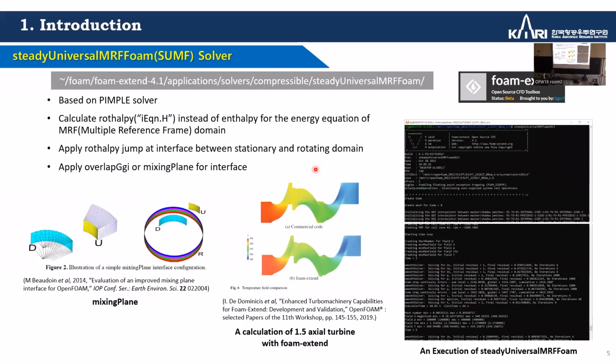What we found is that some researchers have already done their work, for example with an interface like a mixing plane here, and some researchers have already done work on the compressible MRF solver. MRF means multiple reference frame or multiple rotating frame.